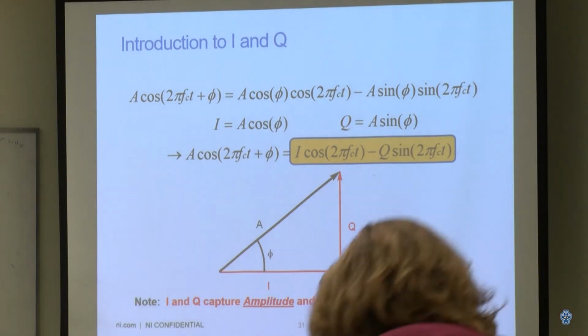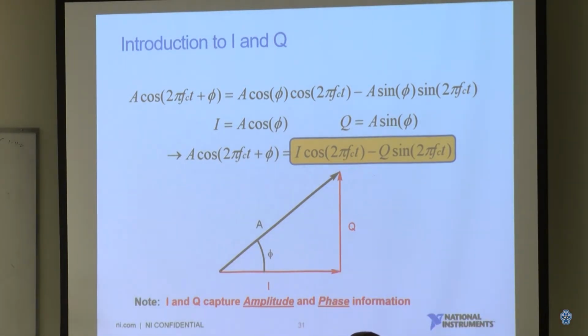Most of the time, measuring amplitude is very easy, since amplitude is just power. But measuring phase is really difficult, because you need a phase-coherent system to capture the original signal phase, and by the time you measure, the phase has probably shifted. Using the I and Q definition can tell you what phase change happened during transmission. This is one of the main benefits of using I and Q to represent the signal.